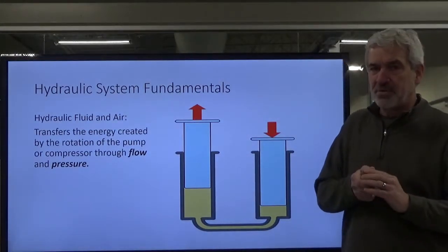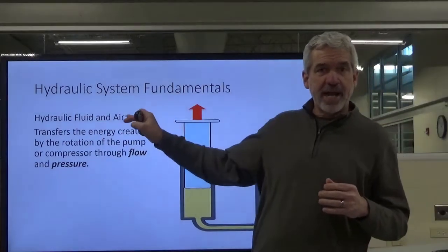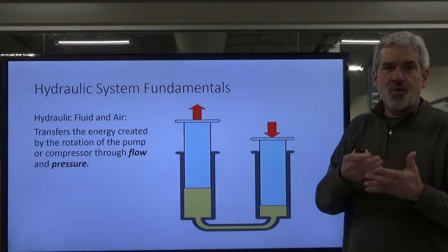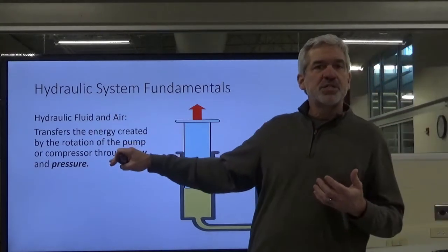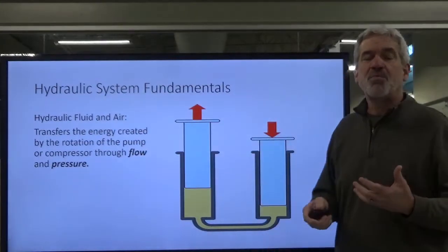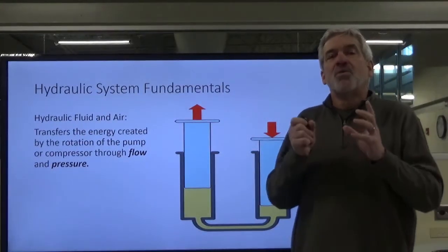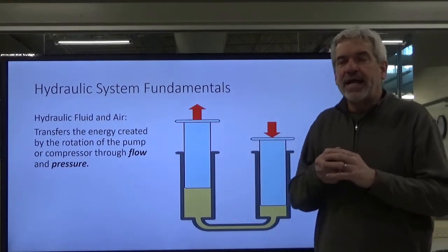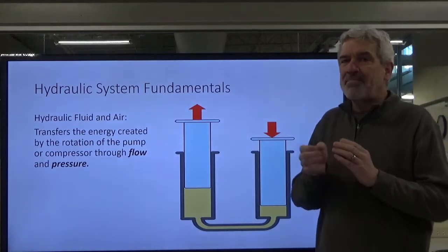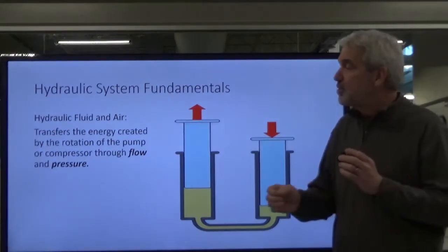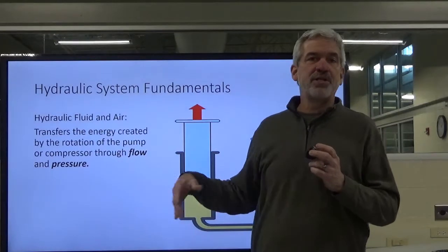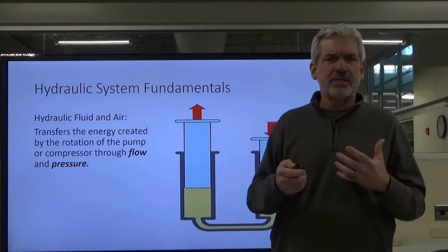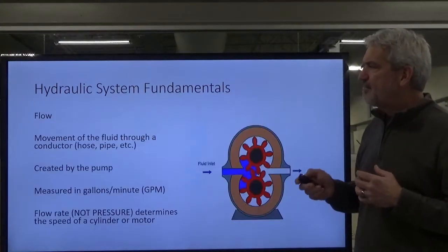Okay. All right. So first of all, we're going to talk about hydraulics specifically for this lesson. We'll get into pneumatics in the next one. With both fluid and air, we transfer energy through the rotation of a pump or a compressor. And what we are trying to create, and this is important, is flow. We also create pressure, and those two are related, but our primary purpose of a pump or a compressor is to create that flow of either hydraulic fluid or air. And as I stated earlier, we're going to deal specifically with hydraulics.